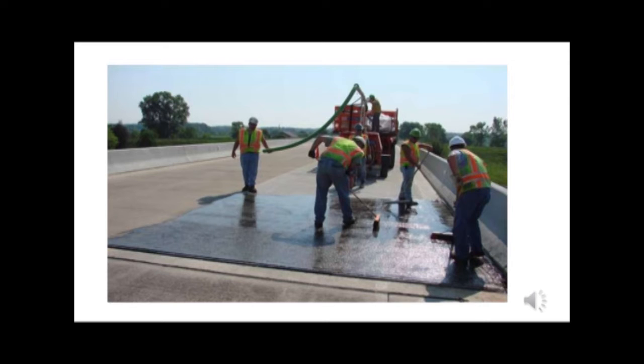So the surface of the concrete, the deck slab, needs to be cleaned. It needs to be made dust free. It needs to be washed, and the nails and the projecting reinforcement need to be cut off. And once it's done, it's open for laying of the seal layer, the seal coat. What the seal coat does is seal every fissure, every crack, or every shrinkage that has ever occurred, or pore on the deck slab, so that the paving process can be carried out.